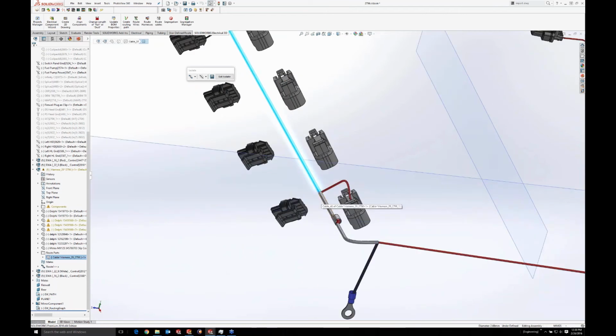Because we know the actual diameter of the harness at this point, I can do things like intelligently choose my harness breakout tees. I can intelligently choose coverings. If we use something like electrical tape, it will actually calculate using the twist method, how much coverage you specify. It'll calculate the linear distance of electrical tape that you need.